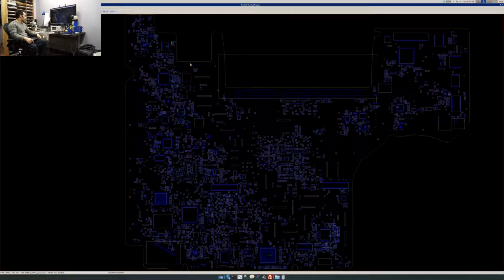So I decided, okay, I'm going to do this the hard way. I removed the battery indicator without removing the connector. Still same thing. I removed the U7000 because it was next on my list, and the short went away completely. Thank God it went away completely, because if it didn't go away completely when I removed the U7000, that would have meant that the SMC was bad, and the SMC is a chip that you replace by removing a bunch of balls that are like 0.3 or 0.25 millimeters and putting them back on, and not something that you want to be doing at 1 in the morning.